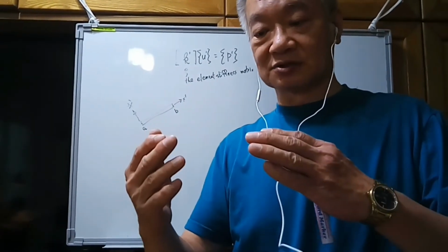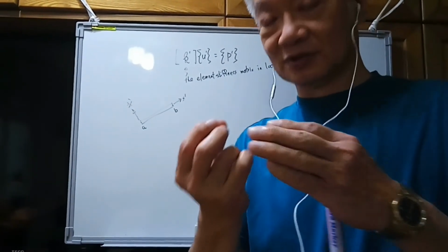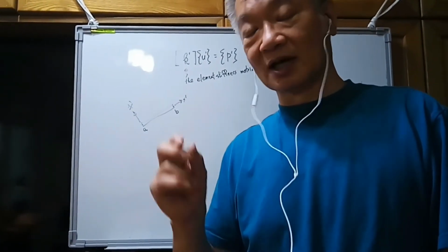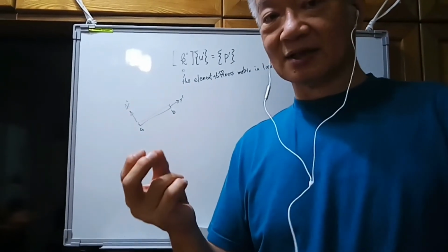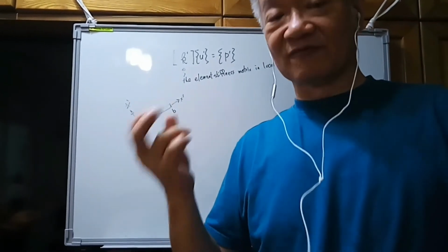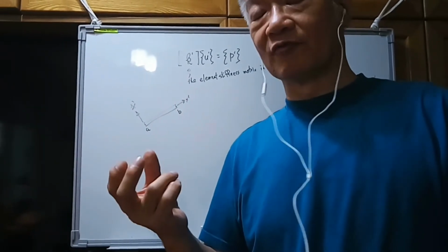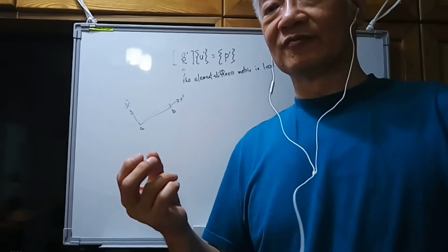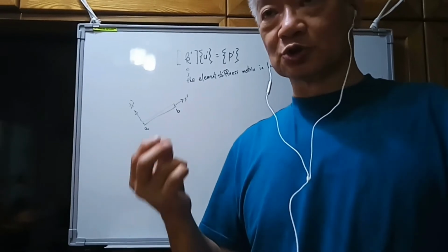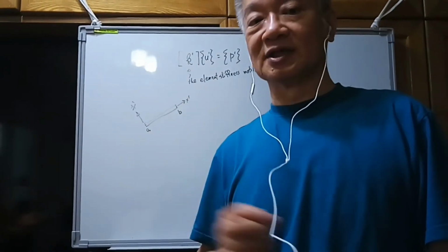But later we need to consider the contributions of the end forces to the same end joint. Then the local coordinate system is not the best choice if we like to consider the contributions from different elements. So at this time we like to transform the vector components from the local coordinate system to another coordinate system. Usually the chosen coordinate system will be the global coordinate system.